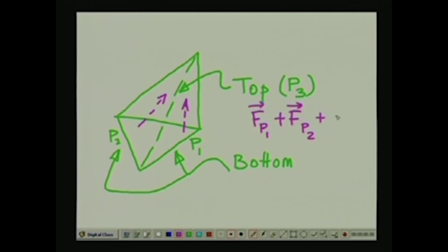and the resistance, because all these things are vectorial quantities, and the resistance because of dilatancy along plane 3, the vector sum of those three resistances, if you add the weight of the wedge to it, then what you should get is a null vector.